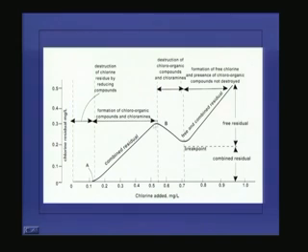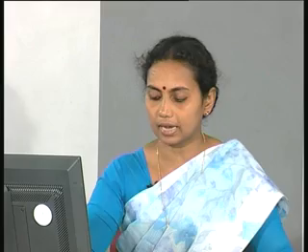Sometimes in water treatment systems, the combined residual chlorine is much more stable compared to the free residual. If you want to maintain the residual chlorine effect for a longer time, then after all the treatment, a little ammonia will be added to the system before chlorination. So some combined residual chlorine will be there, and that will remain in the system for a longer time.